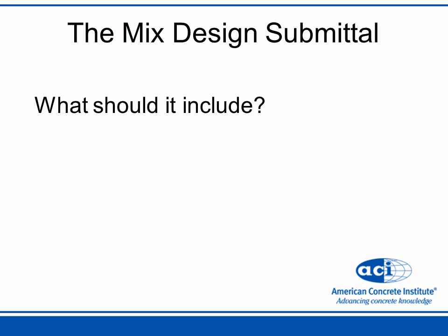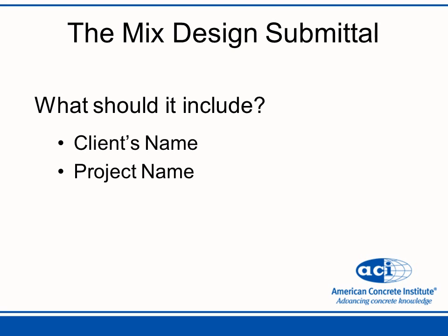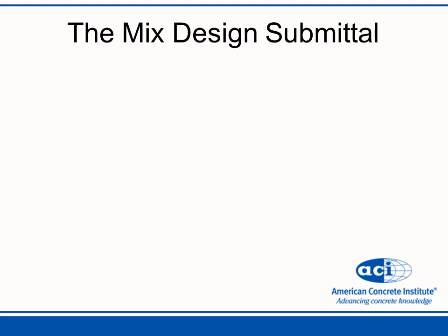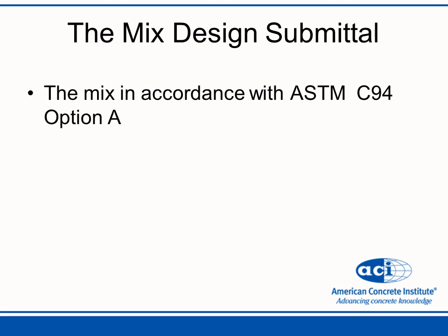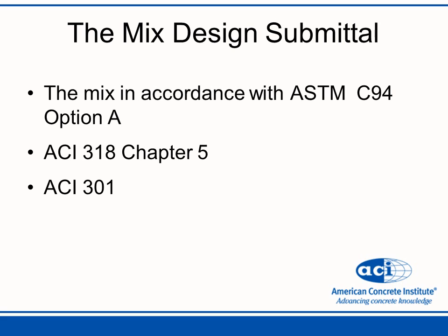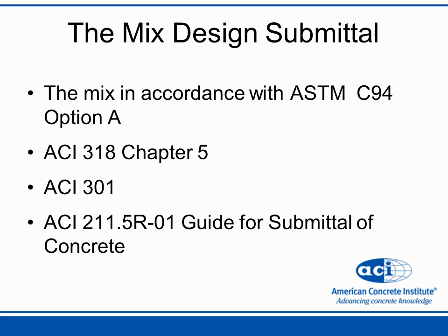The mix design submittal should include the client's name, the project name, a location of the project, along with the bid date, because many times projects are bid and you don't get a request for a submittal for at least 6 months. And the mix design submittal should have everything, and it would then be in accordance with ASTM C94. It would meet the requirements for 318, ACI 301, and ACI 211, the guide for submittal for concrete.